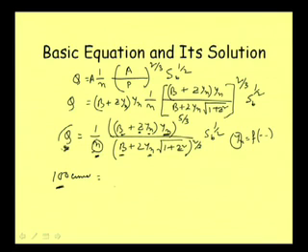not. If not, suppose it has become 60 Q max, that means it is less than what it should be. That means the depth you are considering in the first trial is not sufficient. You need to increase this depth.